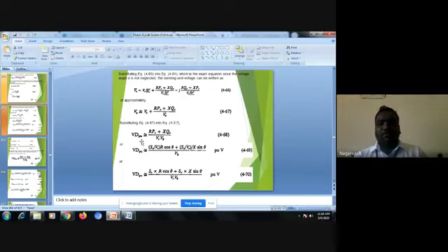What is the R value? It is Sb divided by Vr, that is apparent power divided by receiving end voltage into cos theta. I am substituting that. So voltage drop per unit is equal to apparent power into R into cos theta plus S into X into sin theta, divided by receiving end voltage into base voltage. This is about the voltage drop per unit value. When I go for the per unit base voltage, I will get this. Okay, this is about the voltage drop.